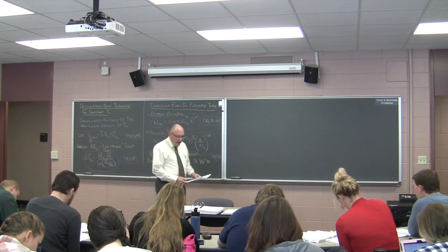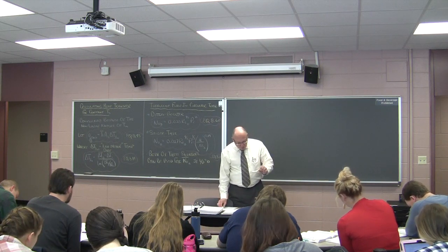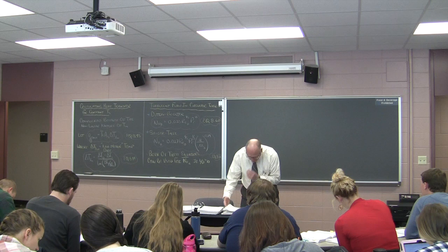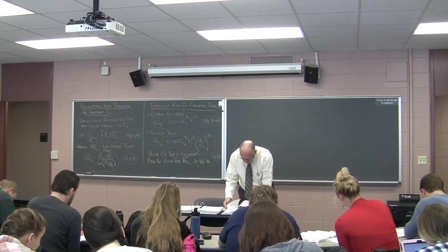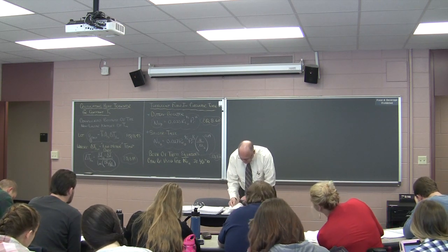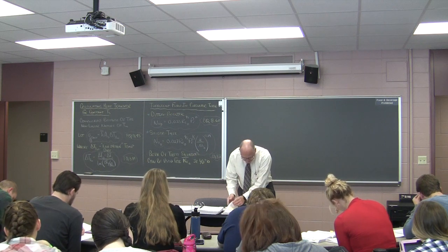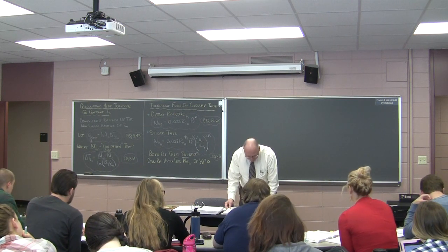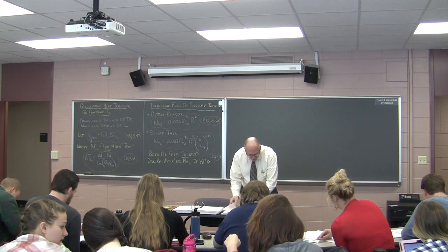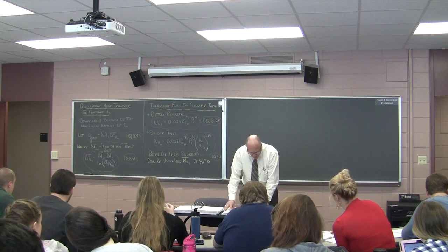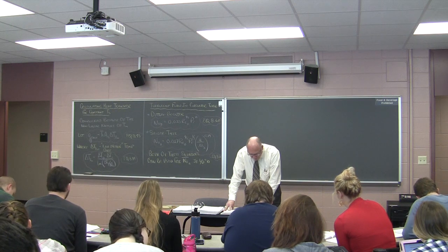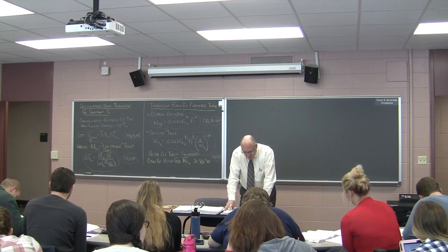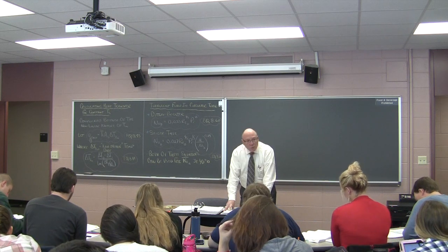Now, let's take a look at these equations for a moment. Go to your book, and open it up to page 516 in chapter 8. All right, look at the conditions for the Dittus-Boelter. Turbulent flow, fully developed. Prandtl numbers of 0.6 to 160.